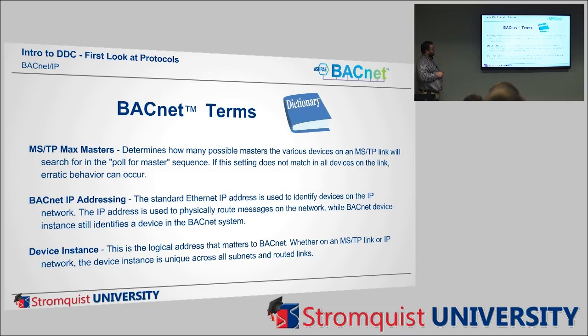BACnet IP addressing, use a standard Ethernet IP address. So the same kind of address that your computer uses when you get on the Wi-Fi or you plug into the wall. And device instance, what we talked about, that's the software address of the device.